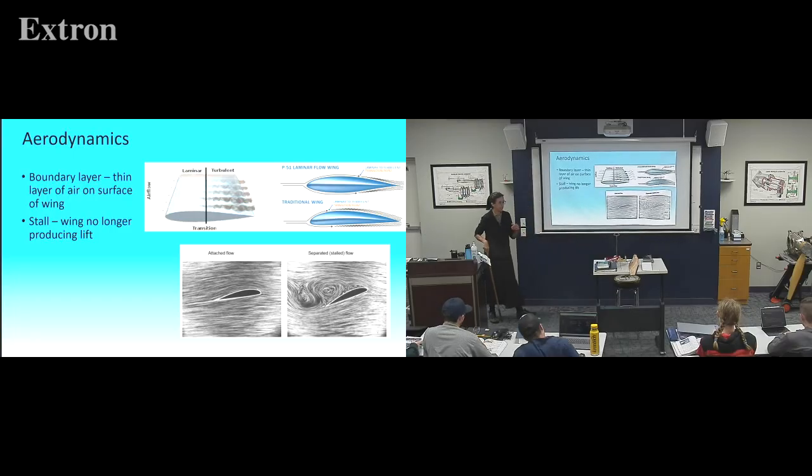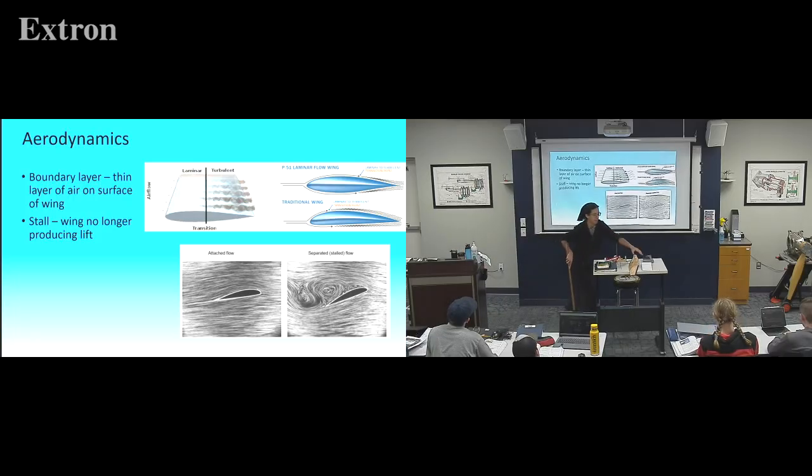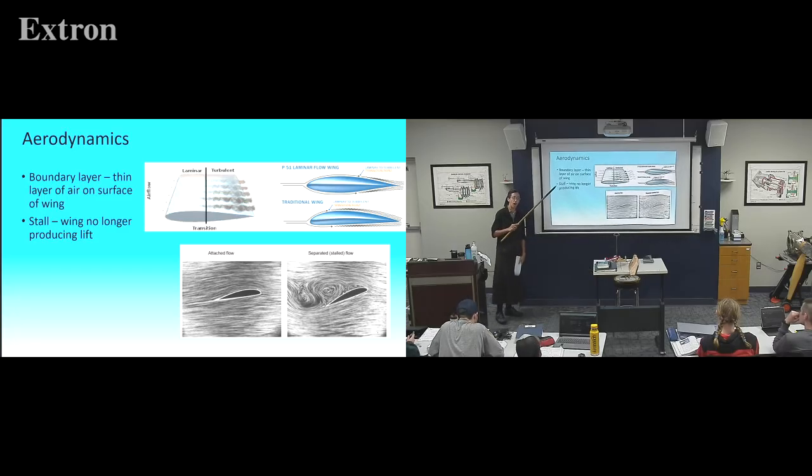And the more turbulent you are, well, as you increase angle of attack, you saw in another video, there's a point where that transition area moves forward, turbulence is happening closer and closer until finally drag overcomes lift, down we go. So the stall has nothing to do with the aircraft engine.